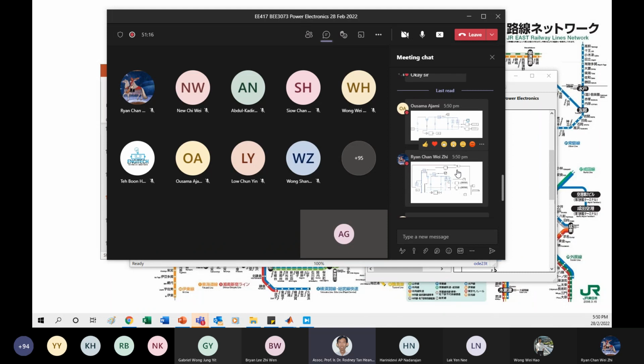Okay, that's why you can see the theoretical calculation does not take into account the voltage drop across the turn-on resistance as well as the voltage drop across the diode. Normal diode will have like 0.7 volt, right? Remember, if you want to increase efficiency and reduce the voltage drop, you may need to consider using the Schottky diode. Schottky diode will have a very low, like 0.2, of voltage drop. So that will actually help to improve the efficiency.